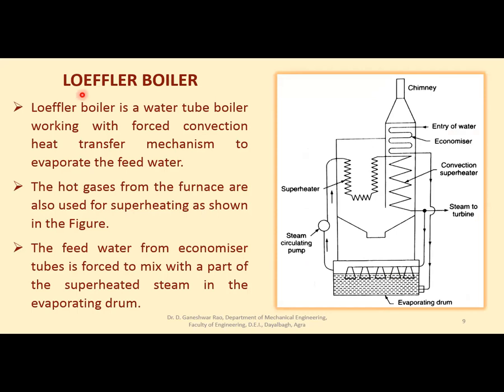The next boiler is a Loeffler boiler. In the Lamont boiler, the major difficulty experienced during its working was deposition of salt and sediments on the inner surface of water tubes. What will happen due to that deposition? That will reduce the heat transfer and ultimately the steam generation capacity, right? So there should not be any deposition inside the tubes, but that was a major difficulty in the case of Lamont boiler.